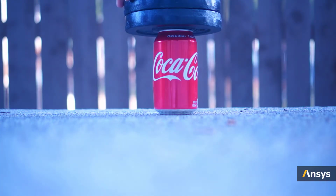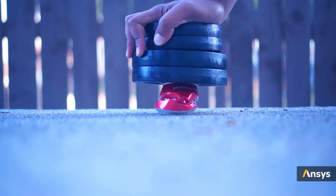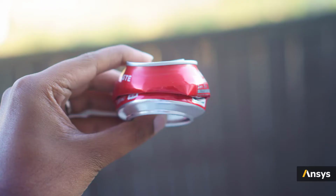Now, we may have the luxury of making approximations with a solid aluminum bar. But if we shift our focus to a similar loading in case of a thin hollow structure such as a soda can, which is made of the same aluminum material, the mechanics change. The soda can crushes under large compressive loads, and as you can notice, there's a significant change in its shape and therefore cannot be approximated as a linear response. These two examples clearly show how large deformations alone can introduce nonlinearity in the system response.